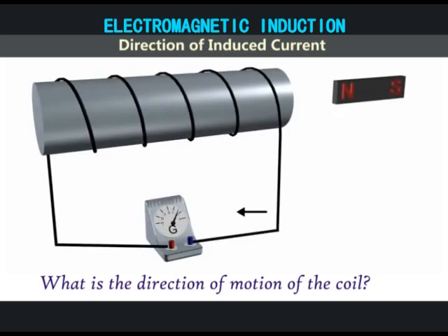Let us now work it out. If the galvanometer needle tips to the right, it means current enters through the blue terminal and leaves through the red, back to the solenoid, and the cycle continues. So at the end near the magnet, considering the winding of the wire, current flow is anti-clockwise.